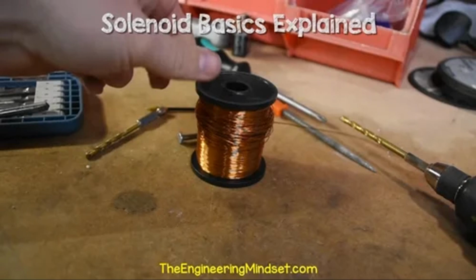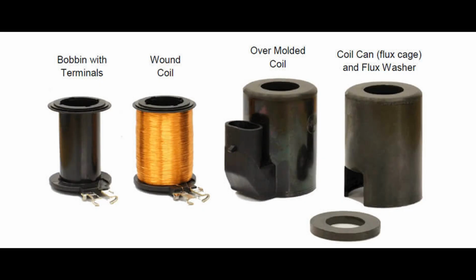Magnetic field and motion. When an electric current flows through the coil, it generates a magnetic field around it. The magnetic field interacts with the ferromagnetic plunger, causing it to move linearly into or out of the coil. The direction of motion depends on the polarity of the current and the design of the solenoid. Force and stroke. The force exerted by a linear solenoid is proportional to the magnetic field strength and the current passing through the coil. The stroke length, which is the distance the plunger can move, is determined by the physical design and limitations of the solenoid.